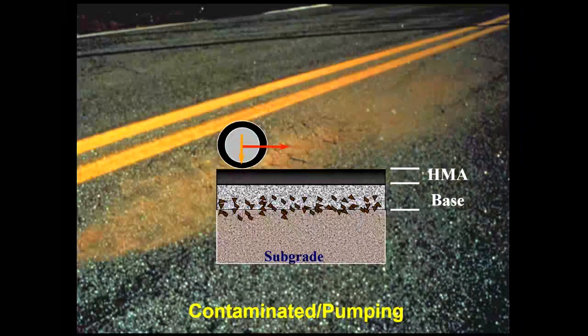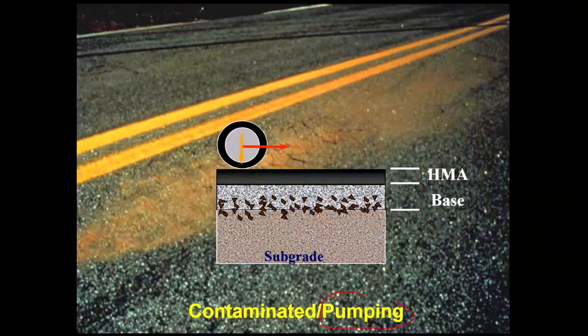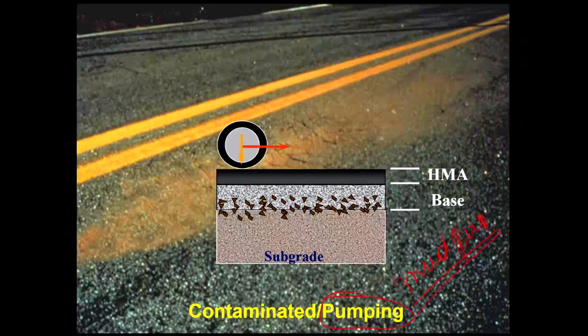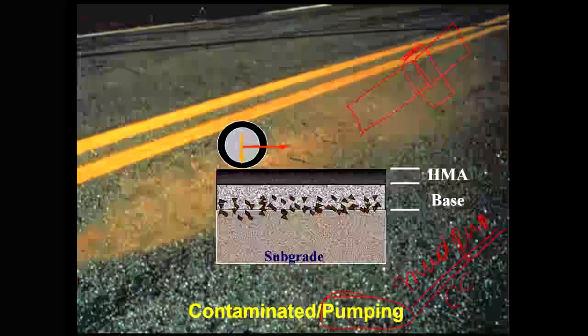In the morning, Dr. Vishnu was mentioning the pumping. Pumping is nothing but what I call mud pumping. Mud pumping is a kind of distress which exists mostly in the CC pavements, and the success of any CC pavement is heavily dependent upon your joint construction and joint deterioration. If the joints are not properly treated and not properly constructed, you can see what happens.